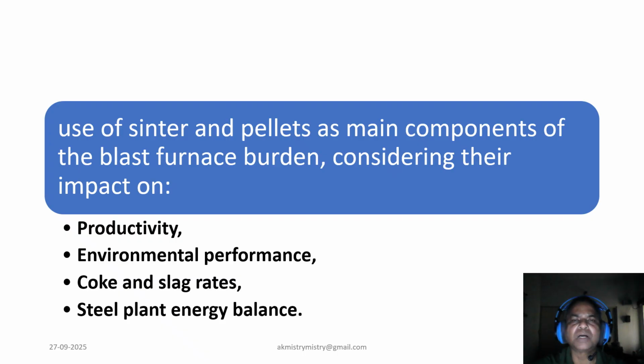So, coming to our economic considerations, from an economic perspective, there is a trade-off. Pellets typically have a higher initial production cost due to the energy intensive beneficiation and induration process. However, these costs are often offset by long-term savings achieved through improved furnace efficiency and reduced coke consumption. Sinter can be more cost effective for integrated steel plants that have their own in-house production facility, allowing them to utilize internal resources and recycled material.